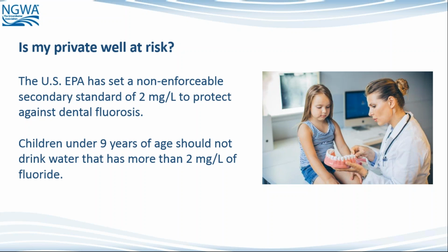So in that secondary standard we're looking at a maximum contaminant level of 2 milligrams per liter, or parts per million, and that predominantly is a great guide for dental fluorosis and, I guess over time, certainly for bone deformation that we saw in some of the other countries across the world.